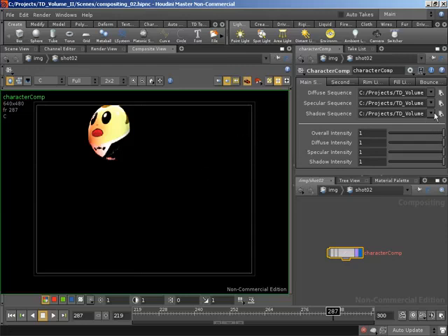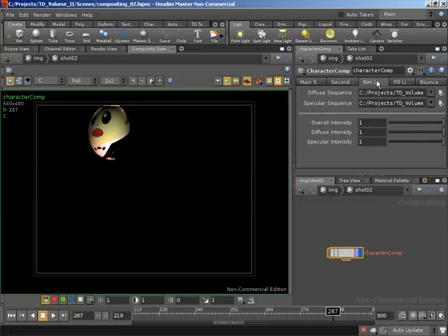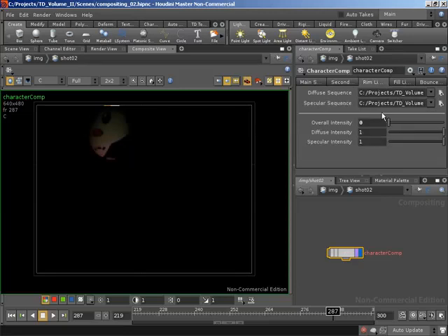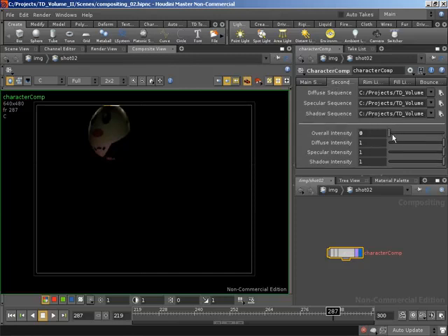So let's start out by decreasing the intensity on all of our lights, and we should see our character turn to pure black. So let's delete the intensity on our main spot. Delete the intensity on our secondary spots, on our rim light, on our fill light, and finally we can see our bounce light. So I'm going to bring our bounce light in subtly. We can bring our fill light in very subtly. And if we bring the rim lights in now, they'll be very apparent with both their diffuse intensity and their specular. And we can bring in these secondary spots.